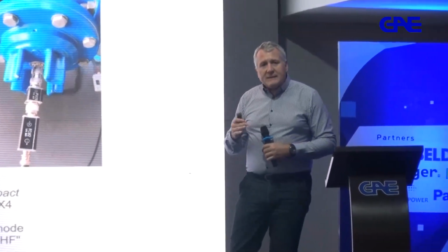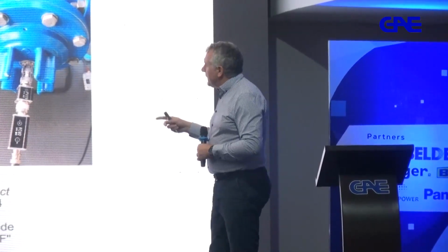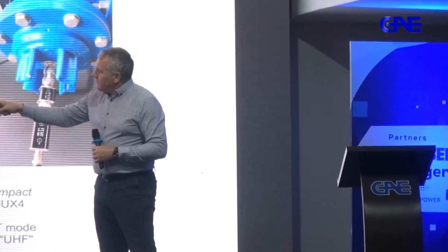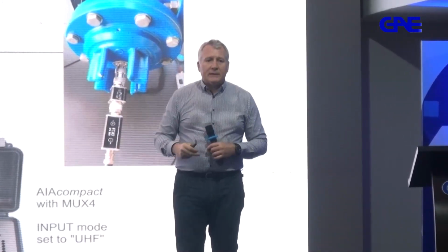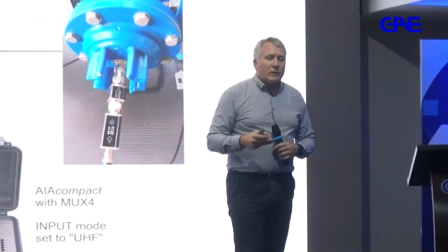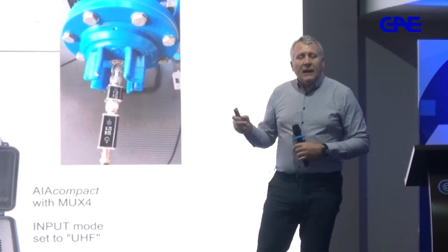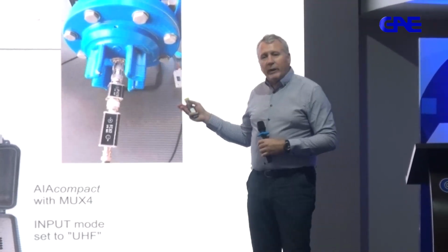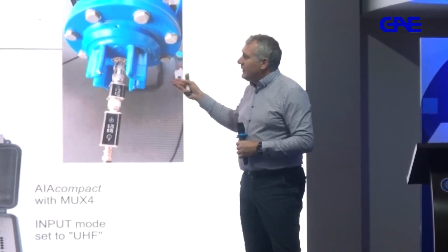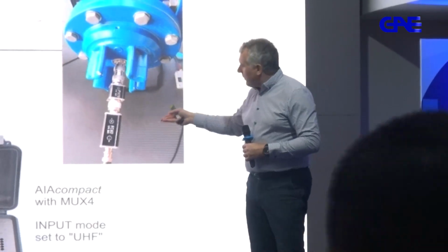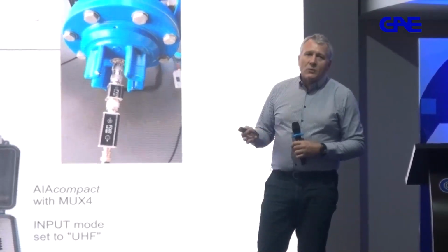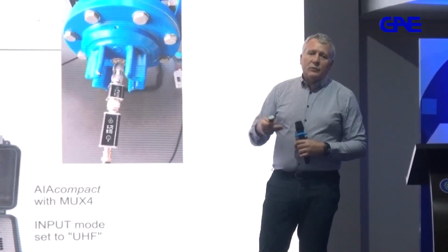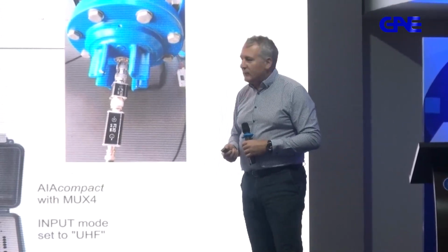So the same device, as I mentioned, in this case in an Explorer case, can be used to look with hatch or embedded antennas, and you can organize a maintenance program for your GIS with a relatively low-cost device and not too much effort, which will require leaving this device a couple of minutes or a bit more to acquire patterns on a regular basis. Of course, this is just, I will say, the easy way instead of doing full monitoring, which will probably be the recommended path going forward.